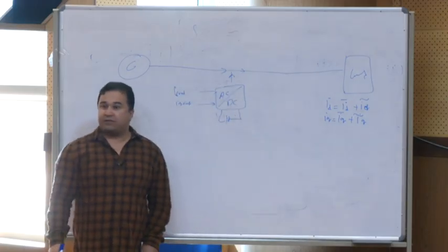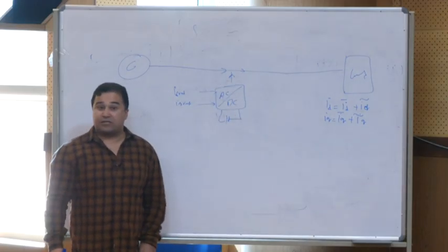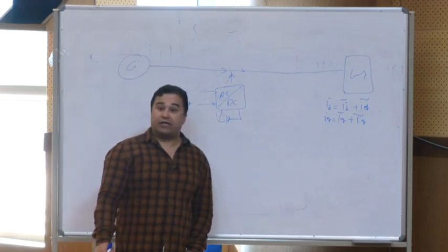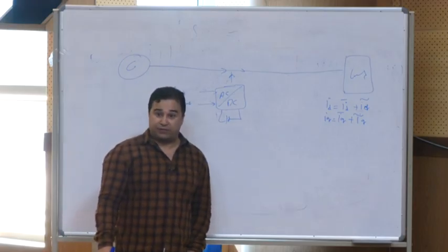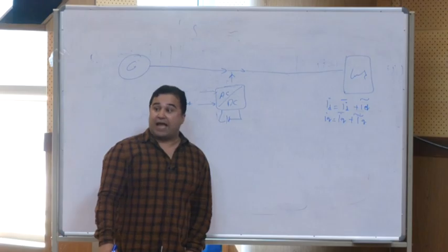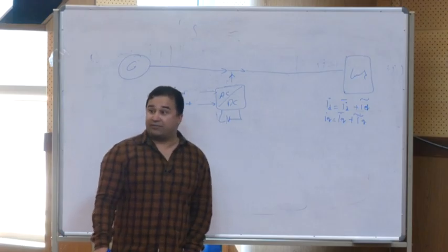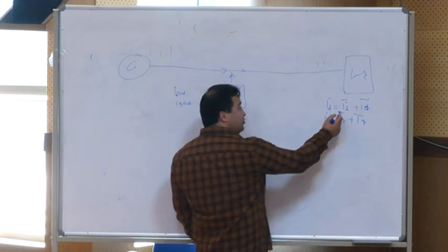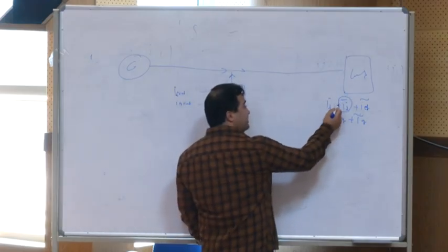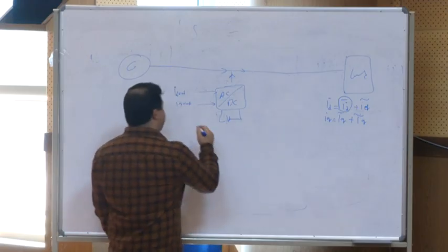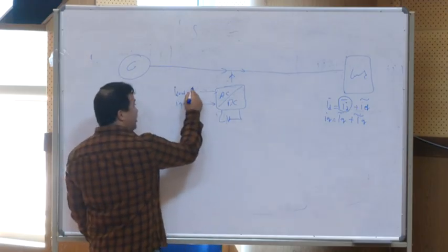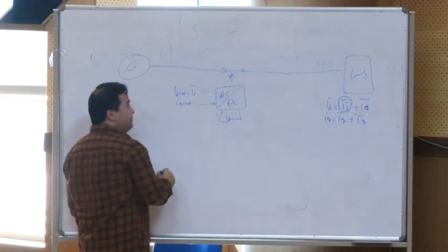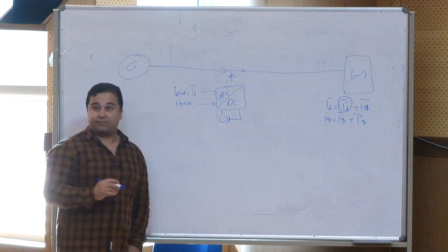Is it fine? So if someone asks you that I'm going to provide electricity like a grid forming with the active power in fundamental frequency, it means that you need just to create this one as a reference. So your reference will be ID in fundamental frequency.